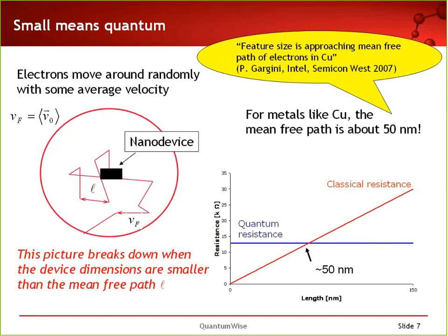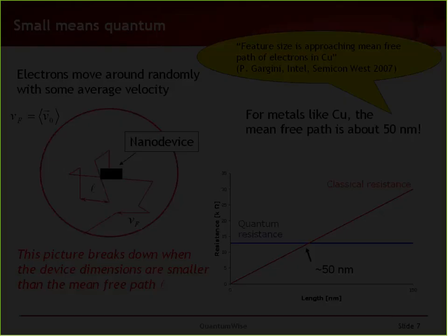So if we are looking at transistors, which are today 20 to 40 nanometers, we are actually coming below this point. We are more in a mixed zone. We're not in the completely deep quantum regime yet, but when we go to 12, 10, 8, 5 nanometer transistor nodes, definitely the picture will change. And for instance, something like mobility might no longer be the relevant quantity to discuss. This is something which is sometimes very difficult for device engineers to get used to. Suddenly the mobility is not my quality index of this channel. There's something else. Things like interface resistance and so on may suddenly be much more important.